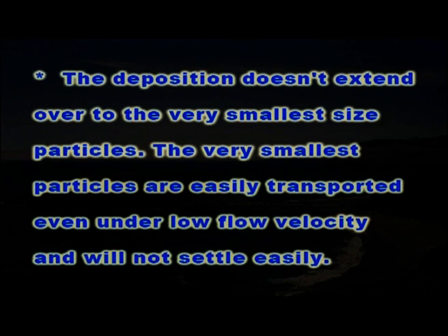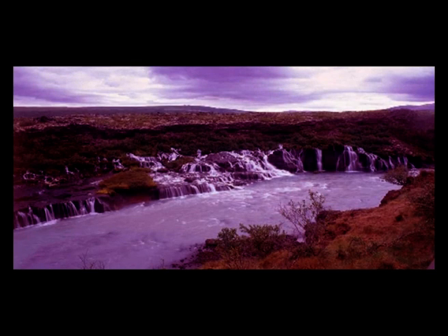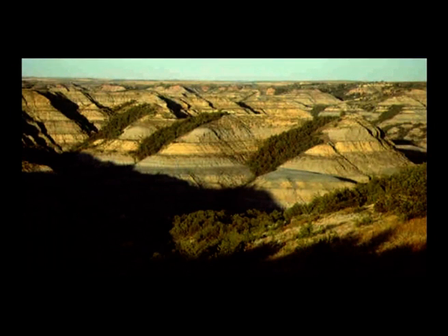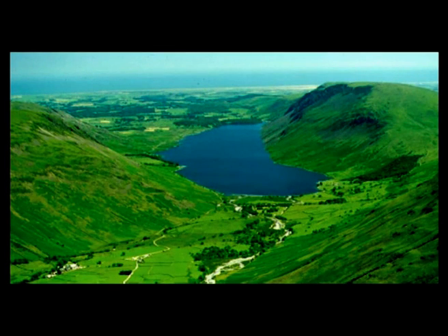The deposition does not extend over to the very smallest sized particles also. The very smallest particles are easily transported even under low flow velocity and will also not settle easily. It is also evident that as the particle size and weight increases, it is very difficult to transport the material and the deposition will occur with a straight drop in the stream. Hence, the landforms which are generated out of these transportation processes are in the middle of the stream course.